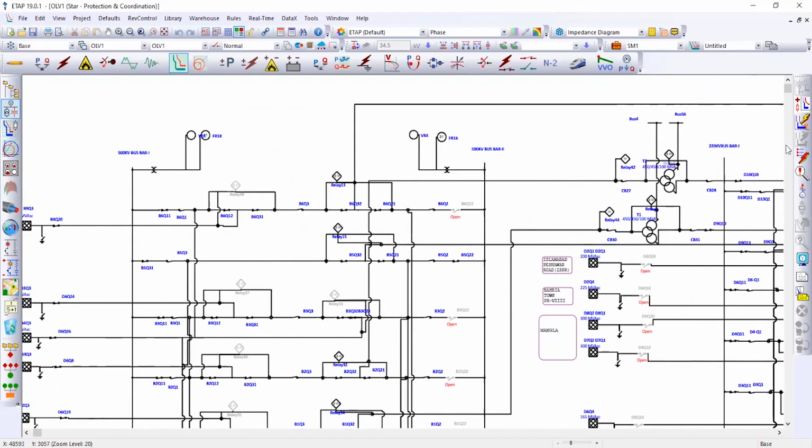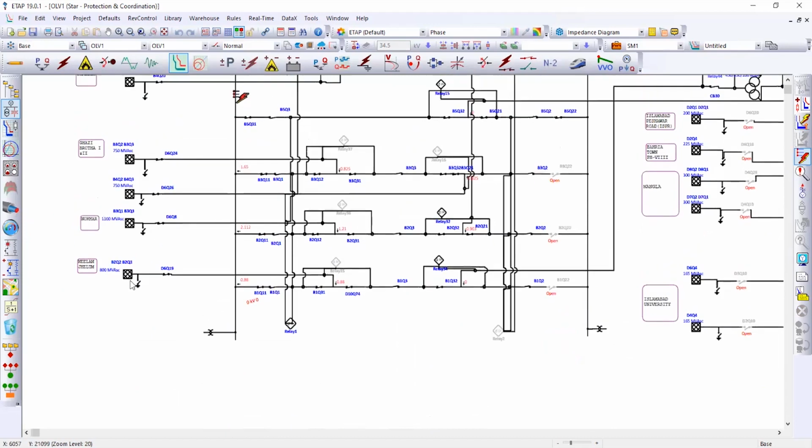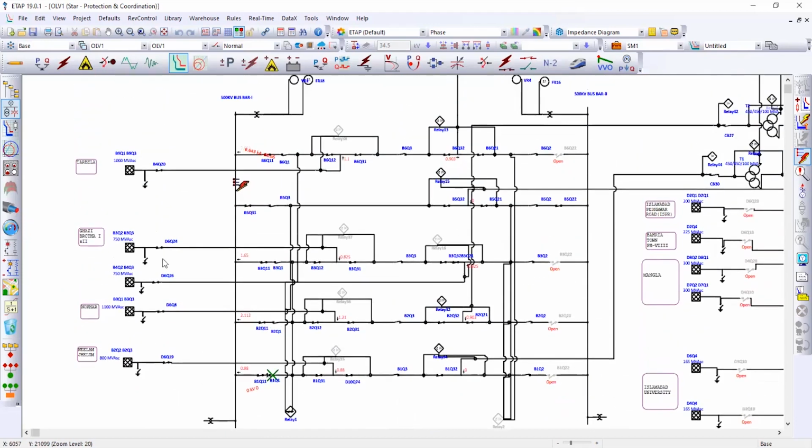Now the final part is the 500 kV portion. And here I'm introducing a fault. This is our main bus bar. The respective circuit breaker will isolate our main bus bar so that the load could be transferred to our transfer bus bar as well. Thank you. That's all.